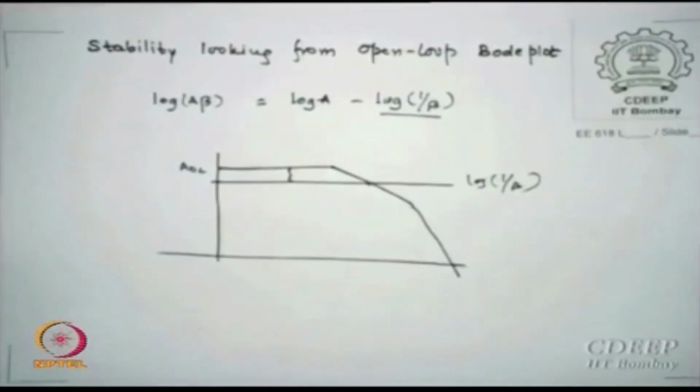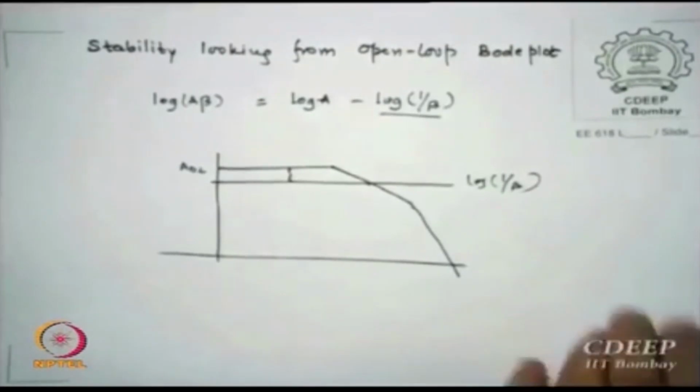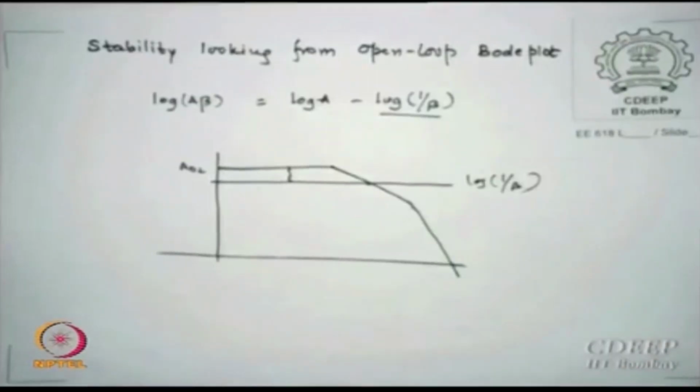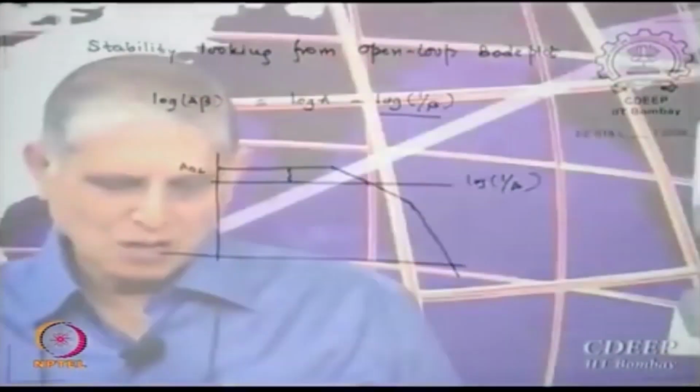So these are some tricks of feedback networks. For those who have done control theory, it may look trivial, but that is what we say: there are different ways of looking at things. Bode's plot actually gives you some idea of numbers, and that is why I follow Bode's plot. Now if you say I can have a phase margin of 45 or above, the issue is still not trivial.